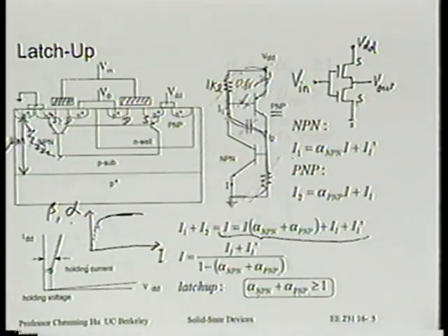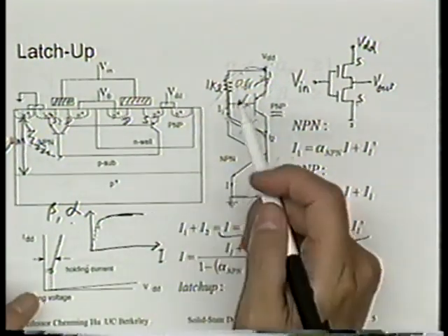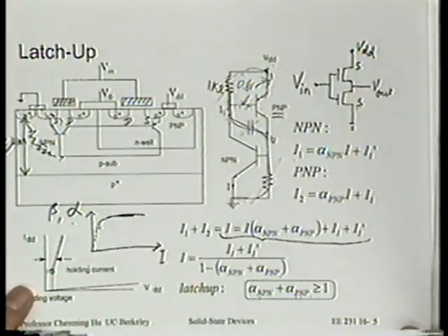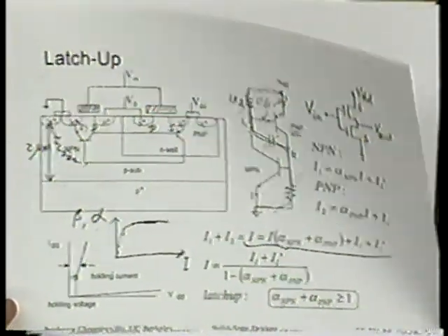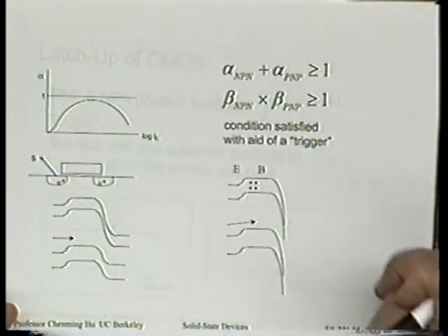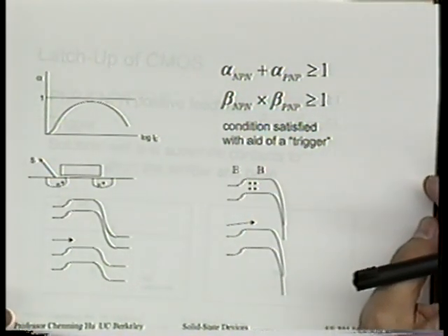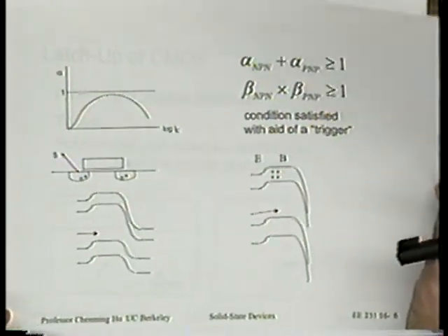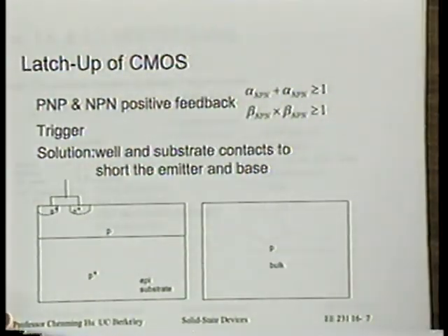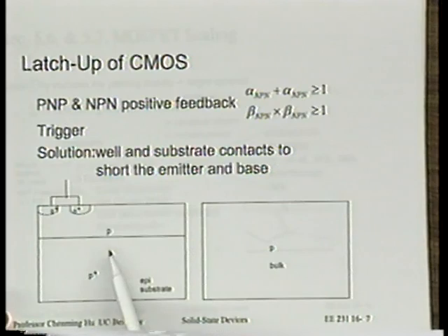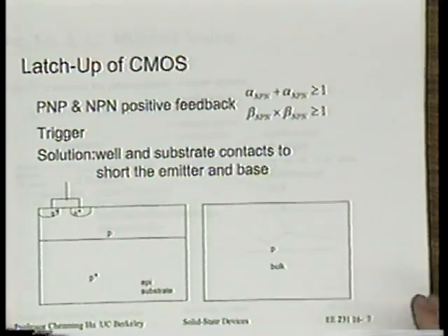Maybe you want to think about it a little bit, and it's particularly easy when you start thinking about the small-signal transistor equivalent circuit, you know, the pi circuit or whatever equivalent circuit. When you add a shunt between the emitter and base, can you see it's effectively reducing alpha? Right? So in a way, you can understand what that's doing there. Okay, I think we'll stop there about latch-up. I already mentioned why adding a P plus epi is helpful sometimes.